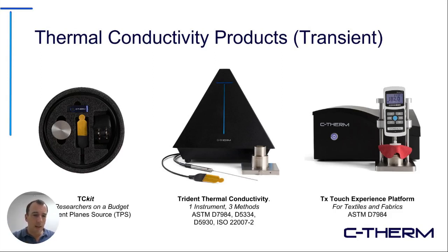And then our Flex TPS sensor, the yellowish sensor there to the lower left, this is a nickel foil that's encapsulated in a Kapton material as a dielectric and is typically sandwiched in between two samples.